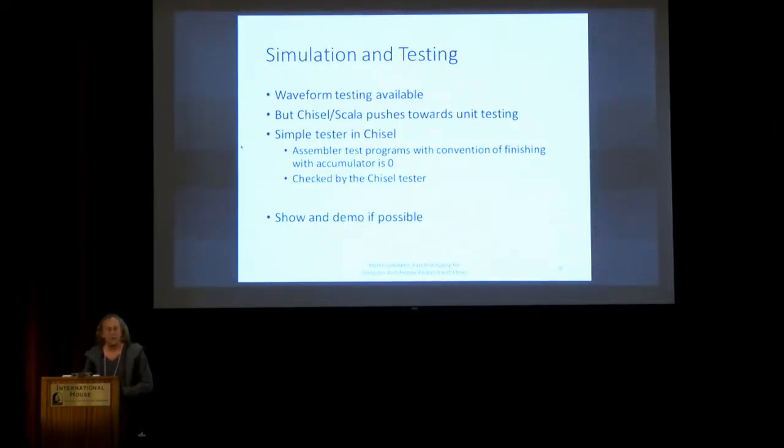Then, when you write hardware, you have to do some simulation, you have to do some testing. Yes, you can start with looking at waveforms, especially in pipelined designs. But actually, Chisel and Scala push more towards unit testing. So let's do simple testers in Chisel. Let's have an agreement that all test cases should end with a 0 in the accumulator. And then, yes, running those small test programs.